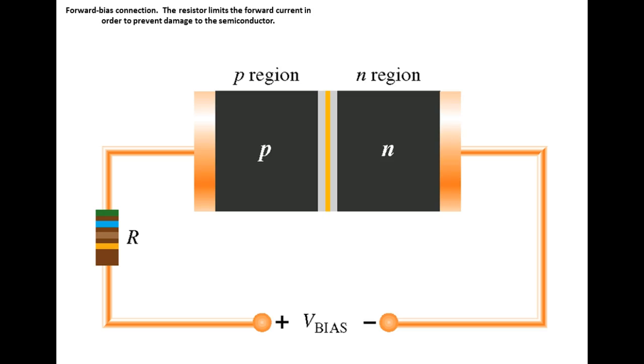So this is showing, I got a resistor. What size resistor is that? Nobody knows. So green is what? 5, blue is 6, and then brown. 560 ohms, plus or minus 5%.